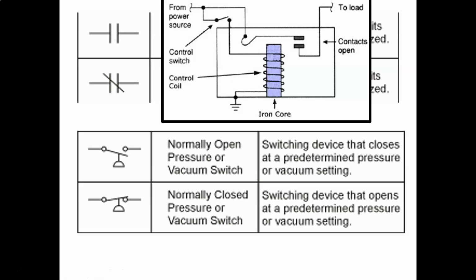Okay, so they're going to be showing you different control devices in different operating states, and you have to determine if it's normally open or normally closed. Right, so if I pushed this guy open right now, if there was pressure in here or vacuum, I could ask you, hey, is this a normally open or normally closed pressure switch?